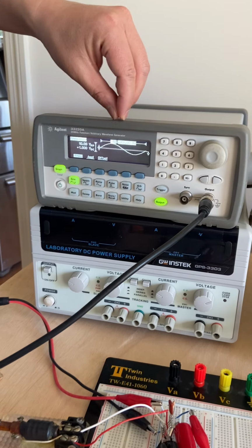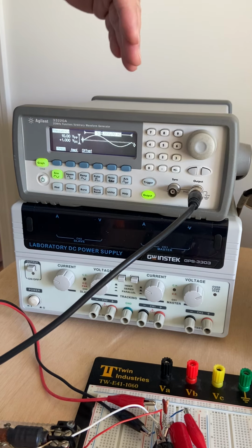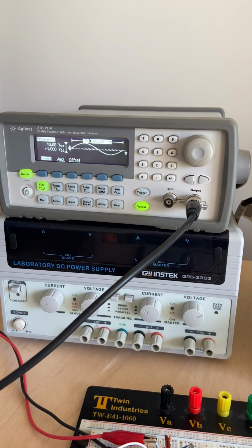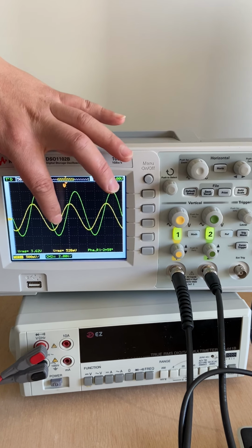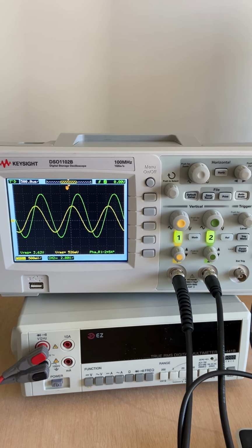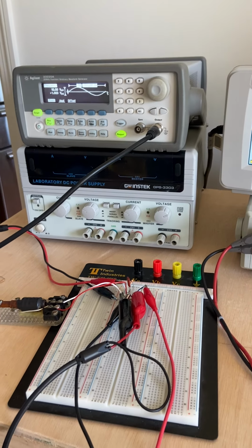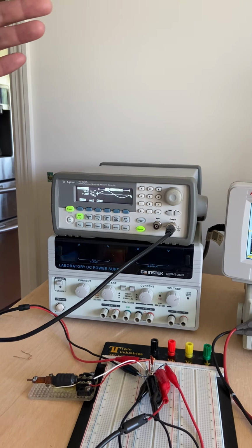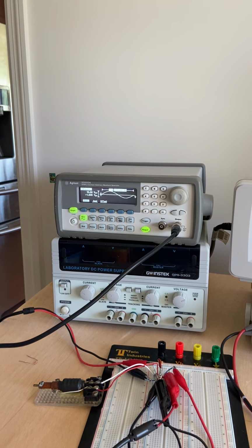Then I'm going to increase the frequency from 500 to 1000 to 1500 to 2000 to 2500 all the way to 10,000 with a step of 500 hertz. At each frequency point, I'm going to re-record the amplitude for both the input, the green curve, and output, the yellow curve, and the phase shift between the two curves. Finally, you will see an Excel file in the Nexus with 4 columns. One column for frequency, the second column for the amplitude of the input, the third column for the amplitude of the output, and the fourth column for the phase shift between the two sinusoidal waves.